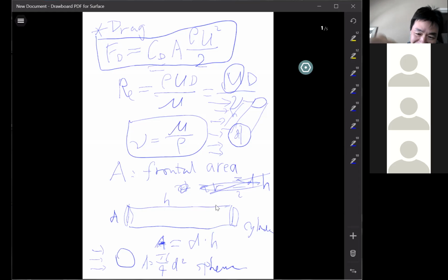Then the ball flies much further because the drag is smaller. So that's the reason why the golf ball has dimples. It makes it fly further. But you still probably need the strength to get to that threshold. That's the difference between a professional and a non-professional. There's a science behind it. If you're powerful enough to reach that drop of the drag coefficient, then you become a pro. So that's about the drag coefficient.